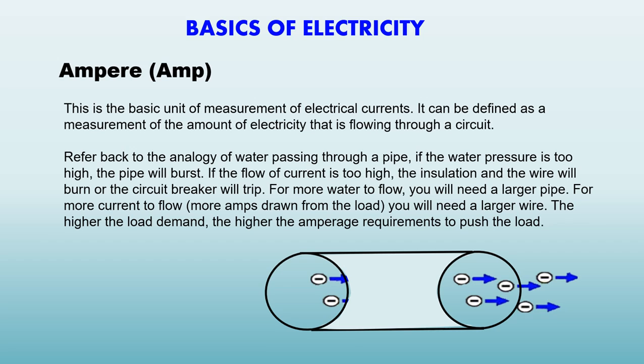Eventually, it's either going to burn, melt, or break. The second thing that happens in this scenario is it starts burning up the motors for the devices you're using. Look at the motors that you're trying to operate and look at the amperage the wires can carry. This will set it correctly so that your wires don't overheat.